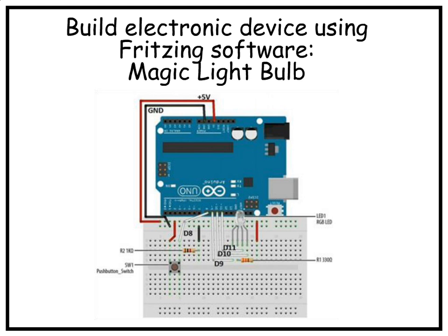Now, the full-size breadboard, it's full, so you got lots of space to add other circuits, do other experiments on that board, and you can kind of make it what I call, you can change the personality of the board, because you can make one section, say, a little DC motor controller project, and then the other side of the board you can make for an LED project. And just by moving these little jumper wires that you see here, you can change the personality of the Arduino, meaning you upload the sketch to the Arduino, and that's where the magic happens, okay? So hopefully that gives you guys some understanding of how to lay out a breadboard.